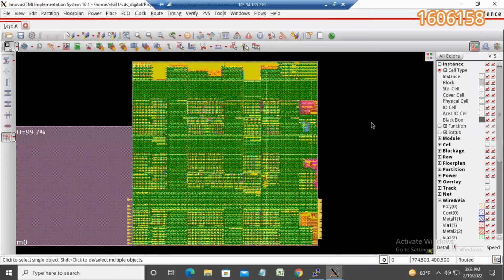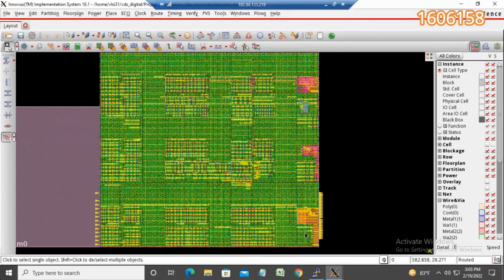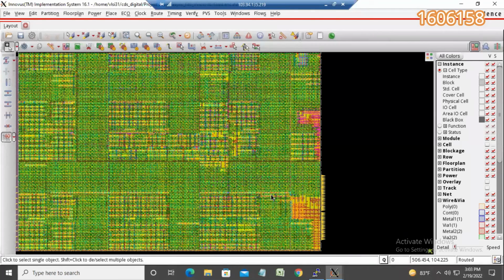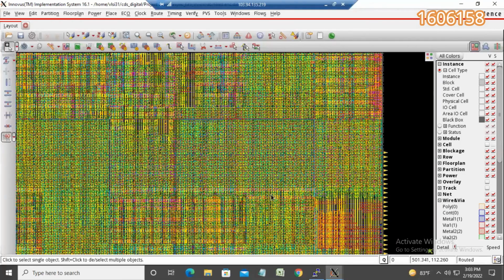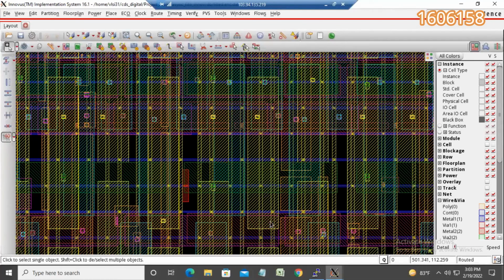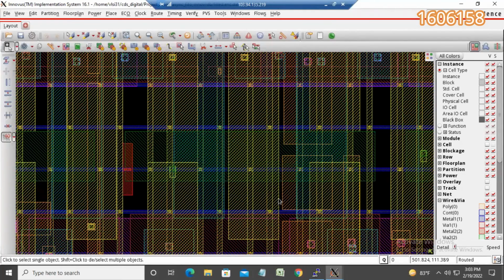this is the Virtuoso layout of our asynchronous FIFO. Here we can see on the left hand side all the input pins are placed. On the right hand side, these are all the output pins. And this is the layout after all post routing, metal filling, clock tree synthesis, etc. As we can zoom in and see the little metal rails and other connections.